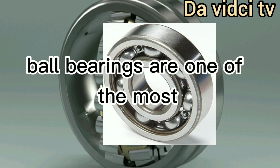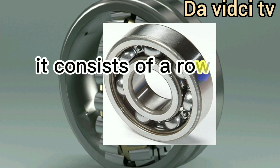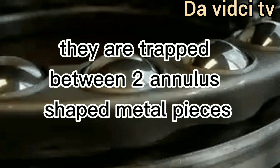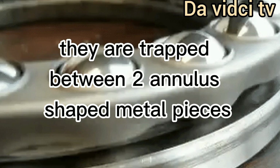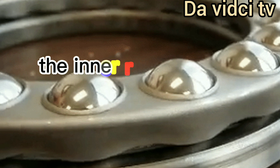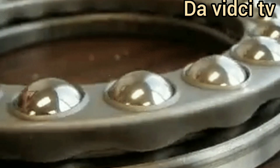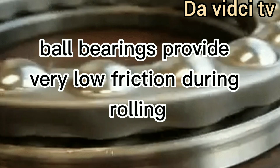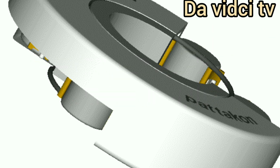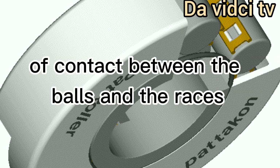Ball bearings. Ball bearings are one of the most common types of bearing classes used. It consists of a row of balls as rolling elements. They are trapped between two annulus-shaped metal pieces. These metal pieces are known as races. The inner race is free to rotate while the outer race is stationary. Ball bearings provide very low friction during rolling but have limited load carrying capacity. This is because of the small area of contact between the balls and the races.